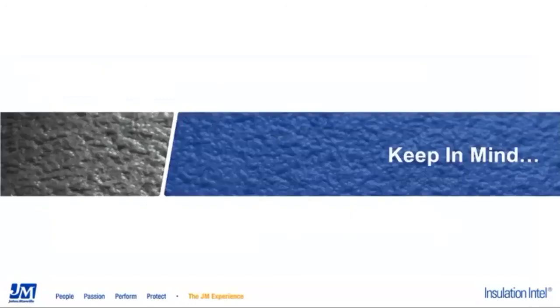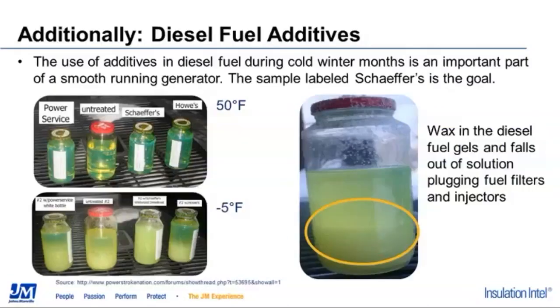And then a last little point here, it's not on the golden rule list. It's just something to keep in mind and know. There are fuel additives out there. Most all of our generators are diesel. This is interesting information for a lot of folks. They've never seen a true study around this. What you're doing is taking these diesel fuels, and at 50 degrees, the paraffin wax that's in diesel is in solution. It hasn't fallen out of solution or gelled. And what happens is, as diesel cools, that paraffin wax can fall out of suspension.